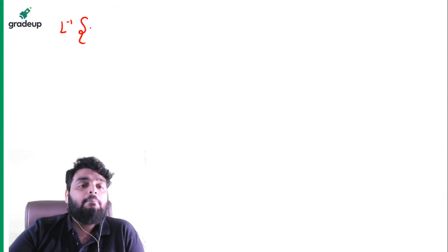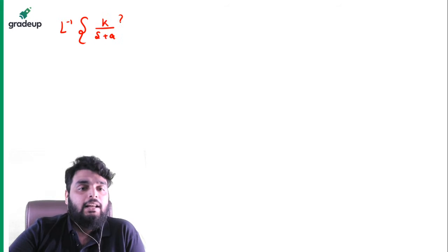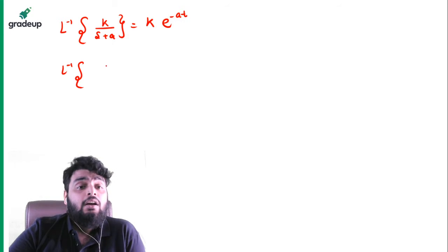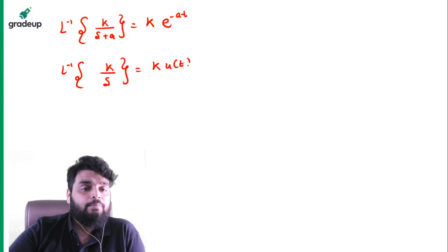Okay. So a few inverse Laplace transforms I want to discuss with you that you should remember for the network. For example, Laplace inverse of k divided by s plus a is k e raised to power minus at. Similarly, Laplace inverse of k divided by s will be equal to k times u(t).